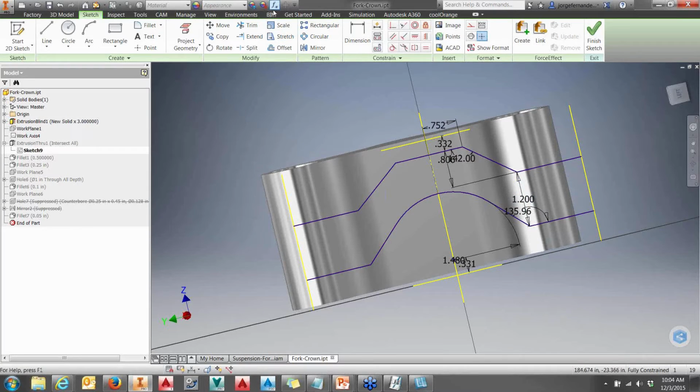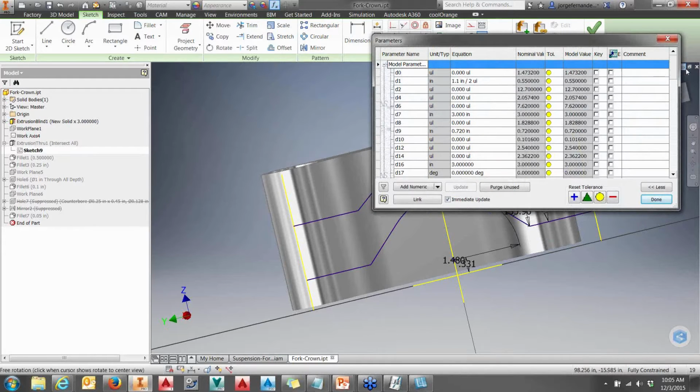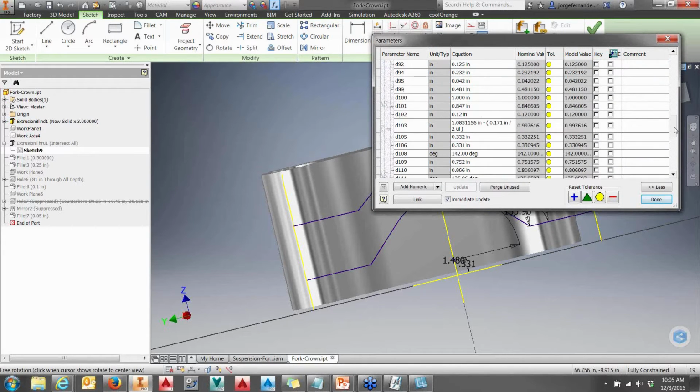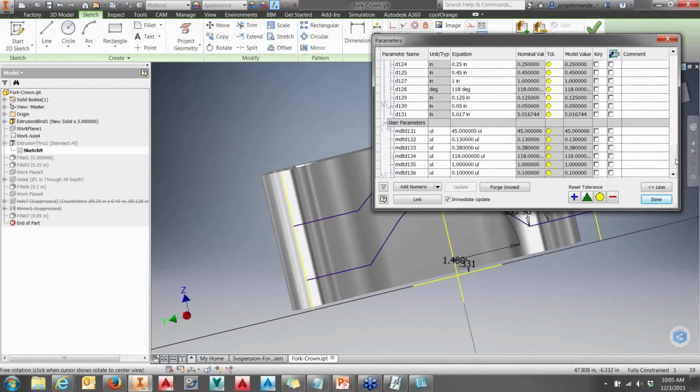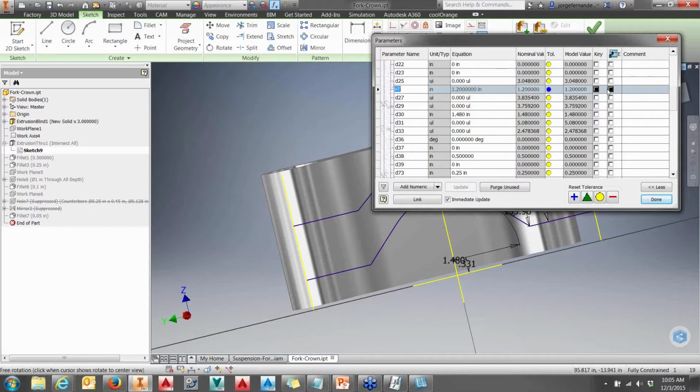And we're going to verify that by going to our parameters up at the top of the toolbars here in our quick access toolbar. And sure enough, we'll notice that HT, I went a little too fast there, sorry about that. There it is. HT is right in here. I'm going to go ahead and select this to be an exported parameter as well, by the way, in my parameters list by selecting this right here.